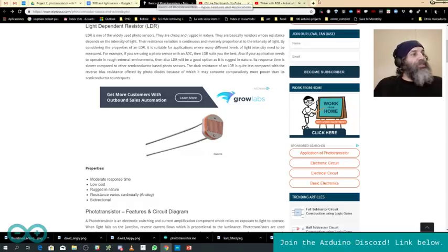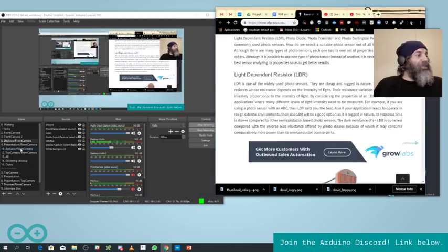So the advantages of each one of those components is something you can check only empirically, and I recommend that you try out different things whenever you have the time, to make sure that you have things that adjust to your needs when you are working on a project. It is very different to use different things, and it's good to adjust the components you have to the situation. For example, an LDR behaves pretty well on your desktop, but the moment you move it to a different environment where the light conditions change a lot, then your whole program tends to fail.